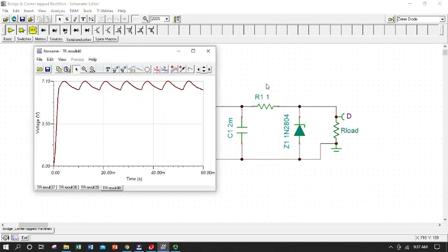So we'll run our transient analysis again, and ooh, nothing really seemed to happen. Our y-axis is at about the same place, our waveform hasn't changed, and we can use our measurement tool again, hit the midpoint, and depending on exactly where we put it, we are within measurement error of the 6.8. We also know that we have more current flowing through this whole part of the circuit. So chances are we're dropping a bit more voltage over the Zener from its internal resistance, but nominally the same.